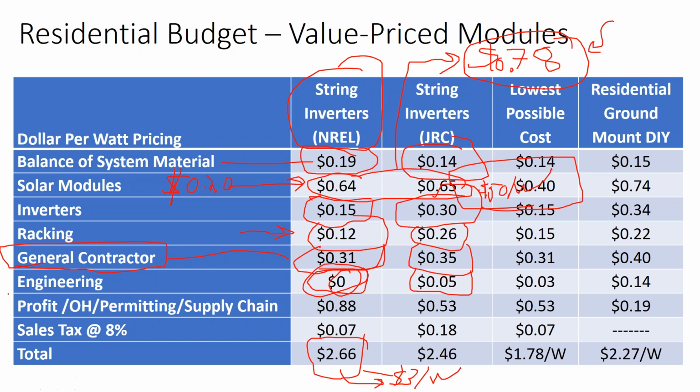So the structural deficiencies in a solar array come not necessarily from the upfront install, but from when it does come time to replace the rooftop. You'll want to make sure that if you're taking the lag screws out of the rooftop as part of the replacement, you're filling in the holes they leave behind with a high strength wood glue to get the strength in the rafter back up.